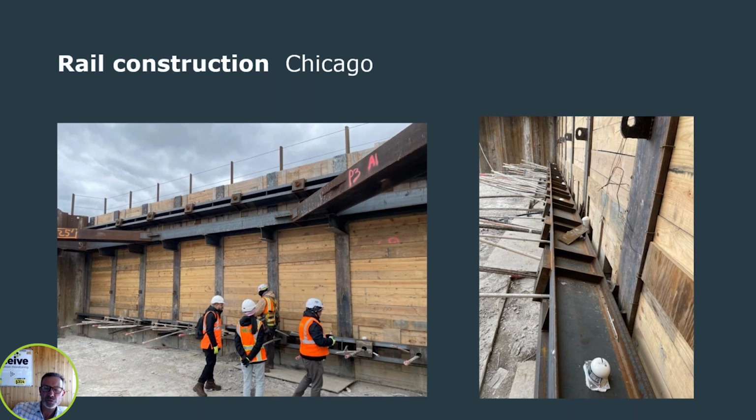And it's a long-term project. There's been Senceive equipment installed on this site since 2022, and it probably will be there for some significant time to come. Right now, I think there are 20 nano tilt sensors installed on these beams, these steel shoring beams inside the excavation. And there are something like 400 nano tilt sensors installed on the sleepers, the track ties, looking at movement of the track itself.